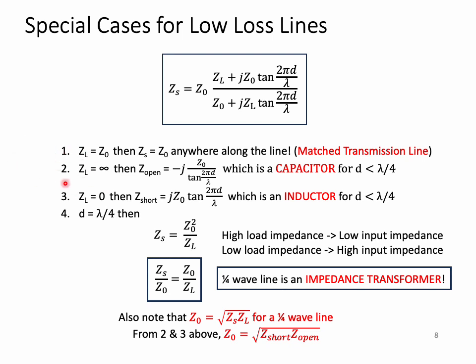These two relationships, 2 and 3, are actually very useful when you're looking at microstrip circuits and you want to be able to make a capacitor or inductor at a specific microwave frequency, because the dimensions are very, very small. So you can make a capacitor very, very accurately by essentially putting an open circuit piece or stub of transmission line on your circuit board, similarly for an inductor.